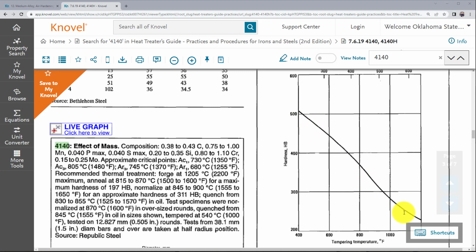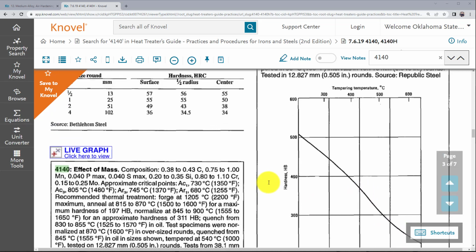And that's another word that we use, draw. So a lot of times we say we're going to draw the hardness down, put it in a drawing furnace. That is a term that metallurgists and people in industry use: let's draw the hardness down, put it in the drawing furnace. So basically we're doing that directly after our hardening. So you're going to have to probably convert that to temperatures in terms of anticipated values.